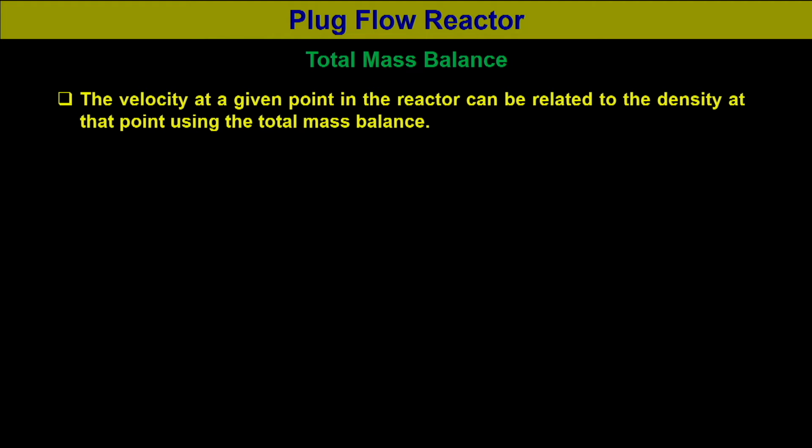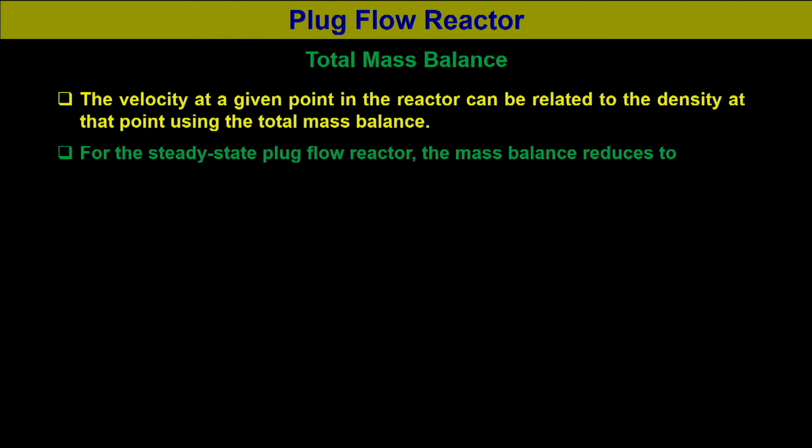So, for steady state plug flow reactor, the mass balance reduces to d/dx of rho Vx is equal to 0.